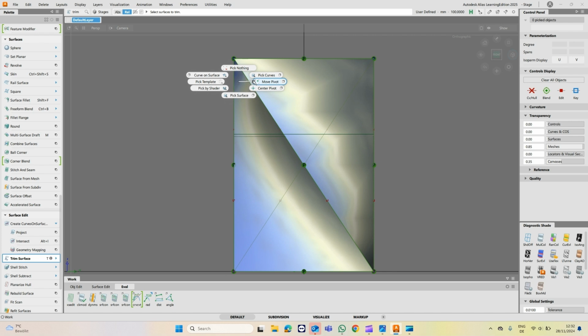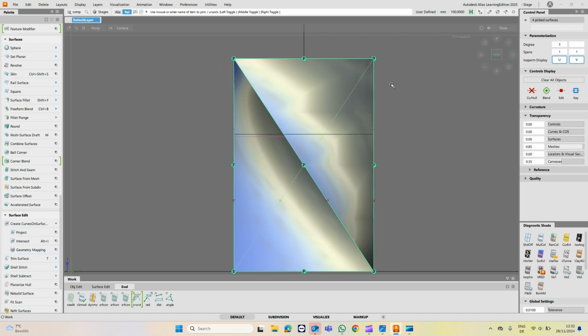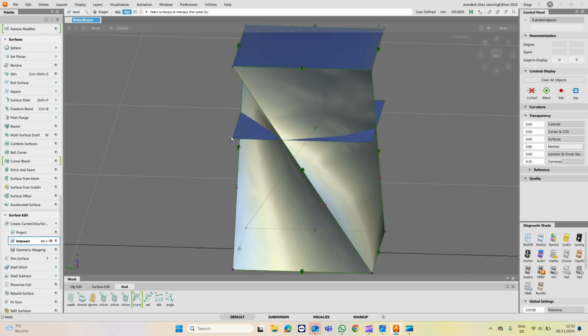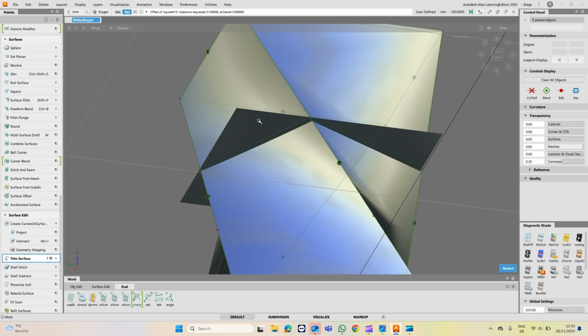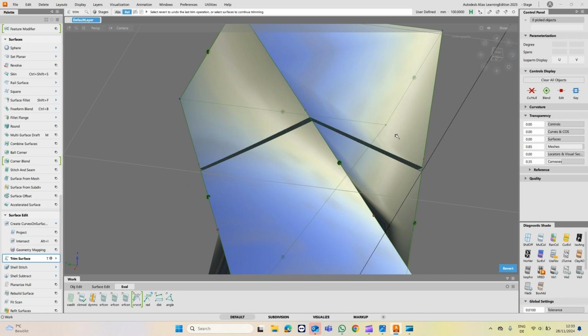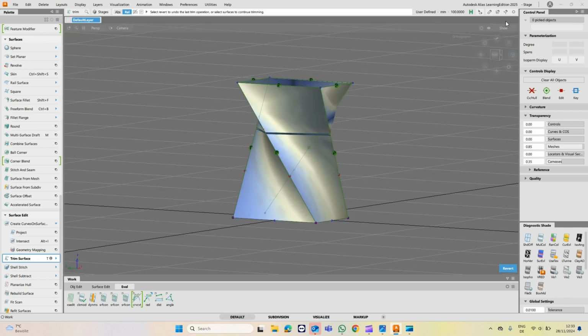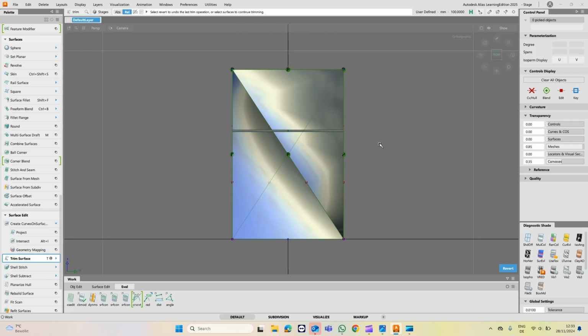And now I'll take these surfaces here. I'll intersect basically with this. Take that. I'll be taking this surface with spacebar. I've accepted that, so I don't need to go with my mouse down there. It helps with the speeding up of our process. Lasso selection, and then trim again. Here at the top. That's it. Now that gets trimmed back to that area there. That's cool. I'll save this up.